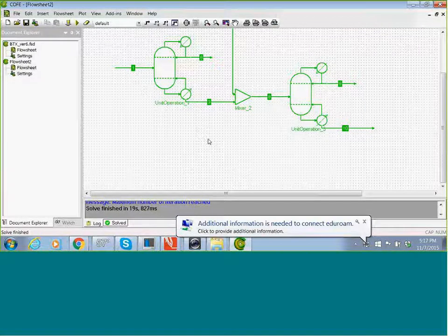You're going to create an Excel spreadsheet, or you actually could use MATLAB, or you could use Python, and create essentially an overall material balance for this paraxylene plant. And it's going to be very simple. The overall material balance is that really all the toluene and the orthoxylene that enters the plant is going to exit in a single stream, and that's going to be our recycle stream.